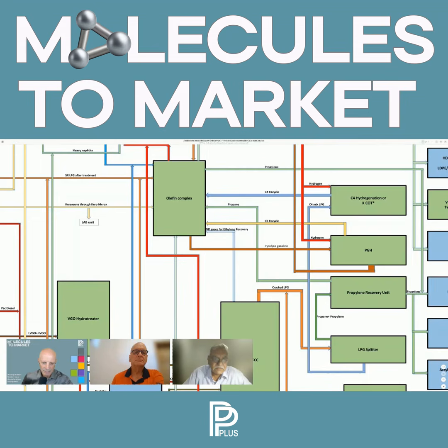So it is approved by the consultant, it is approved by the owner, then it is approved by a statutory body. And unless that approval is there, this document is not firmed up. But once this document is approved, then we don't change it. We can make only cosmetic changes, but the overall concept of the plant does not change because you have obtained all the statutory clearance. Then that particular document is utilized for implementation.